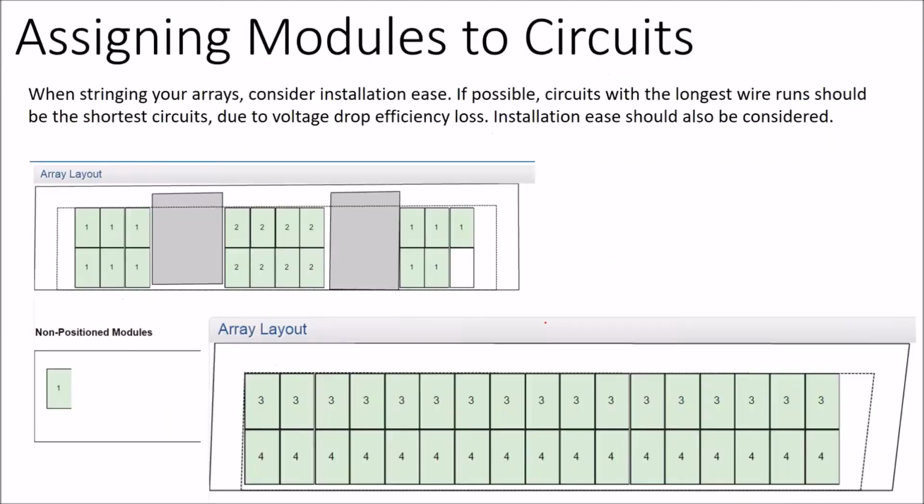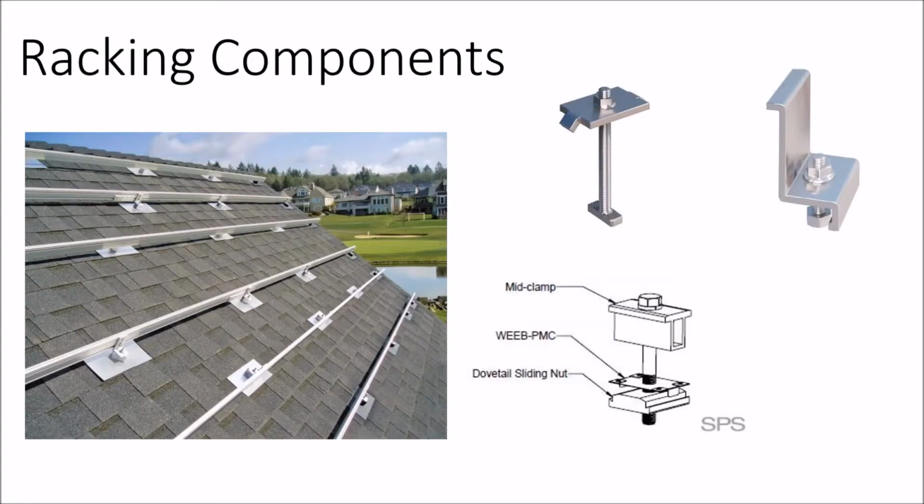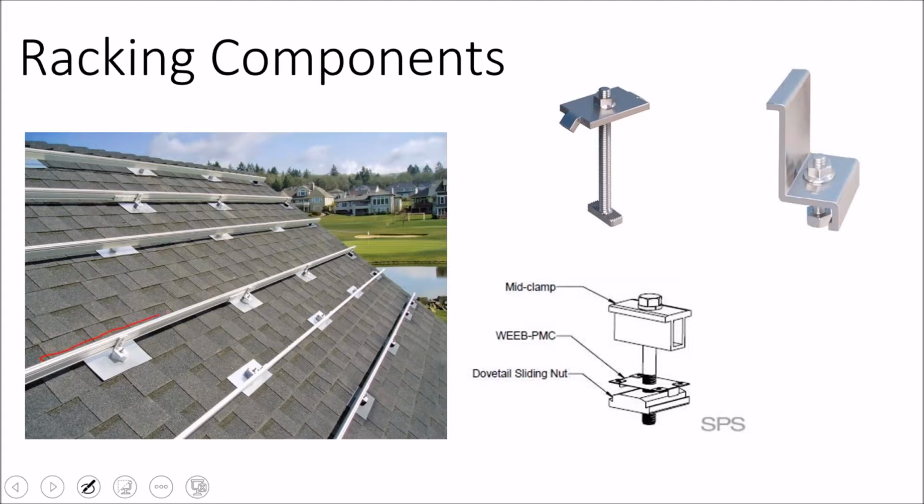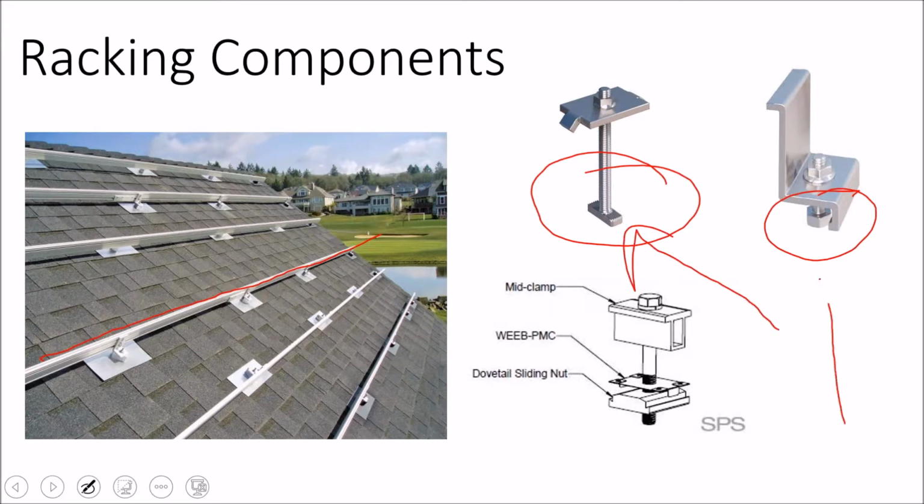Now, another note to point out, on this rail, there's this top channel that runs along the rail. And if you notice in this T-bolt, the question is, here's a hex head bolt and here's a T-bolt. Now, do you have to use a T-bolt? Can you just go to Home Depot and buy regular bolts for the array? And the answer is, yeah, you can. But at that point, there's a channel at the end of the array. And if you use this hex head bolt, you got to slide all of those bolts down that channel.